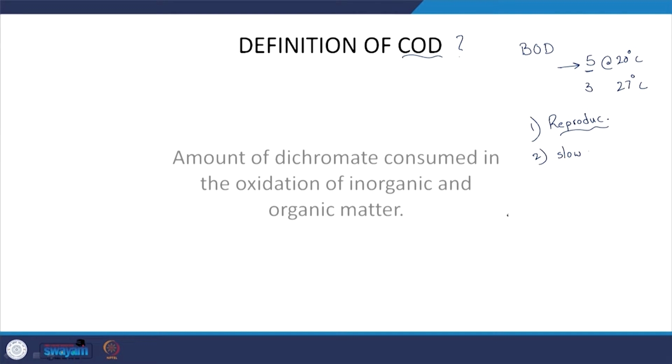So, the COD test, let us say, typically takes 2 hours to maybe 3 hours, yes, so relatively fast. But here we are going to measure both the biodegradable and non-biodegradable organic content, let us say, right. So, that is something to keep in mind. So, how are we getting that done? If I use oxygen for this COD test, it is going to take a lot of time, right.